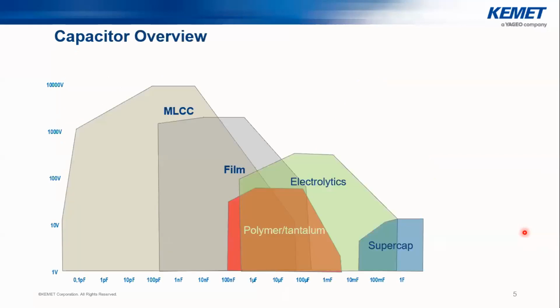When it comes to high voltage applications, we need high voltages especially when we need high power. So either we have to go through high capacitance and high voltages to be able to reach the high power. As we have different technologies for different capacitors, the main two capacitor technologies that can be used up to higher voltages are film capacitors and MLCC, or multi-layer ceramics. Because of that, I focus mainly on these two technologies, and our design is specifically to handle high voltages.